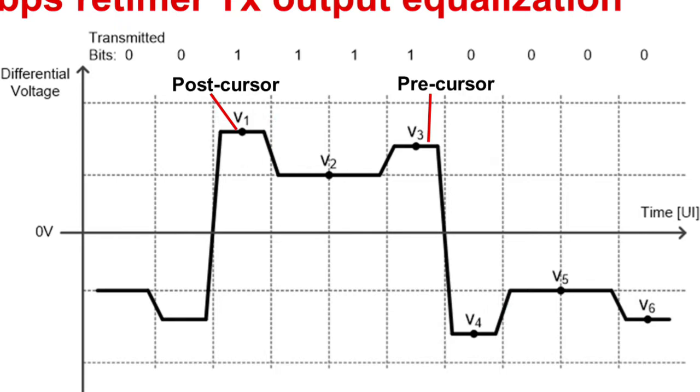To provide high-frequency boost to the post-cursor component of our waveform, de-emphasis may be applied to the subsequent bits further from the transition. By reducing the amplitude of the non-transitioning bits, the low-frequency component of the signal, relative to the post-cursor transition bit, high-frequency boost is effectively applied.